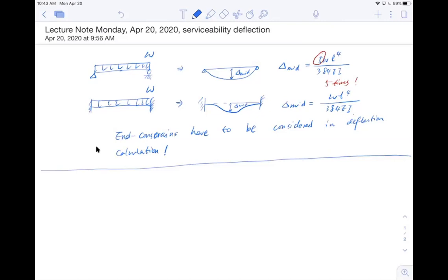The other thing is that I also have a problem like this. Say this is a simply supported beam, a simpler condition, but I have cracks along the span length. If I draw the moment diagram, the distributed load moment diagram looks like that, a parabolic line, remember? And from previous calculations, I have the cracking moment right here.